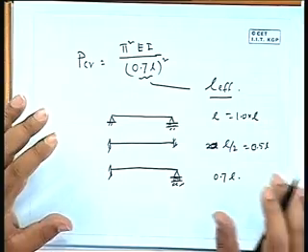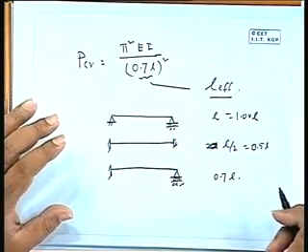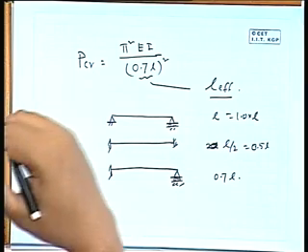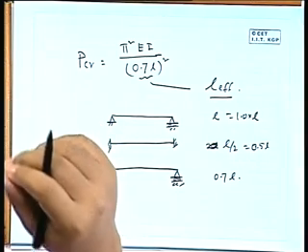You would be happy if we put 0.75. So it is not 0.75, but anyway it will be some intermediate value. If you take 0.75, you are going to take more effective length. So more effective length means it will be much weaker, right? So from your intuition, if you take 0.75, you will be on the little safer side in the design, but the actual value will be 0.7.